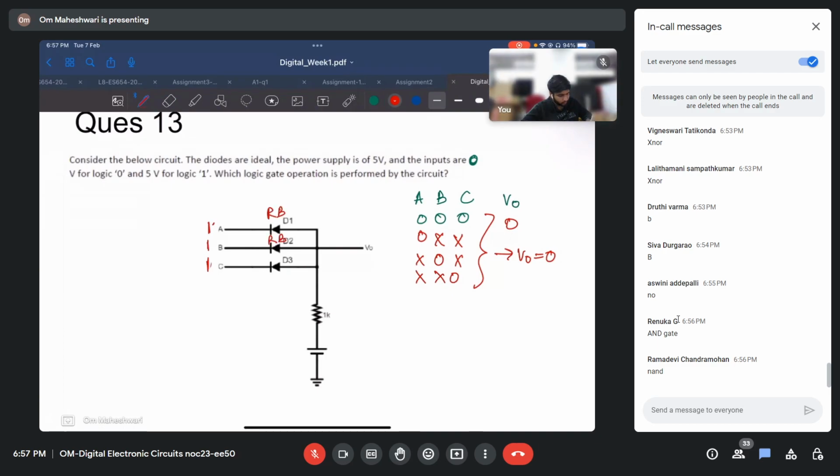Oh, sorry, earlier I spoke reverse bias, but that was forward bias. So when we apply 0, here it is high, it is low, that would be forward bias. So in all these earlier cases, the diode was forward bias.